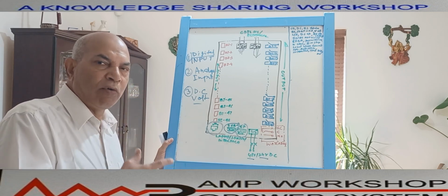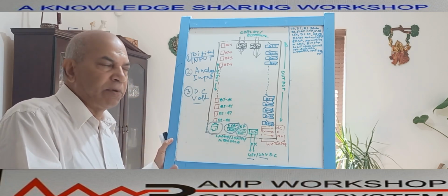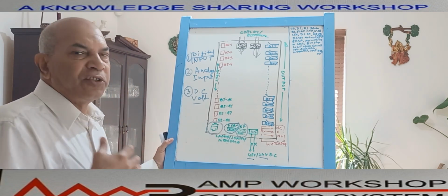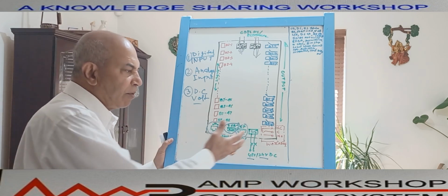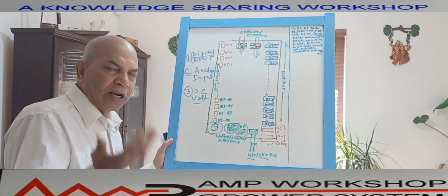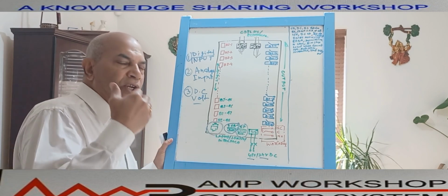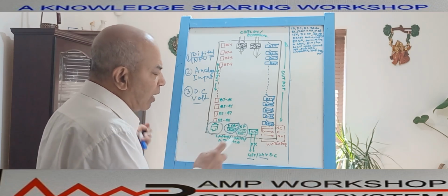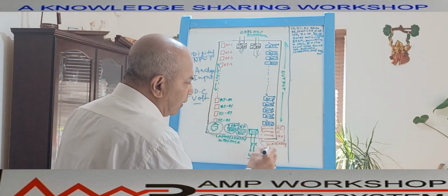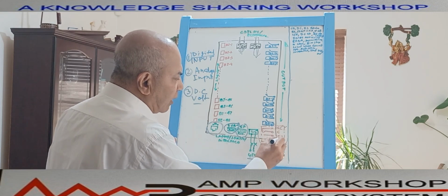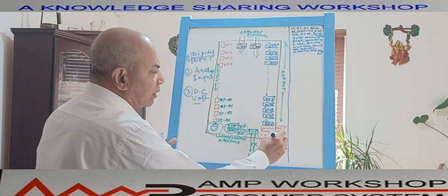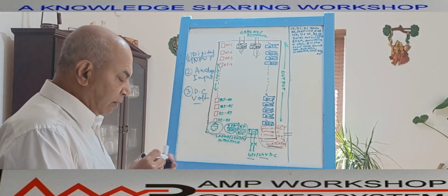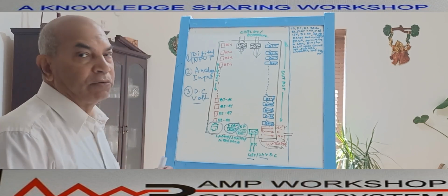But the moment the relay fails, the watchdog system operates immediately and gives a changeover contact, and that changeover contact will give either a red color indication or an alarm to the remote end that the relay has failed. I have shown the output contact only: a changeover contact, this is NC, this is NO and this is the common. This is the watchdog system output. That is also another feature of this protection relay which we can interface with the switchgear.